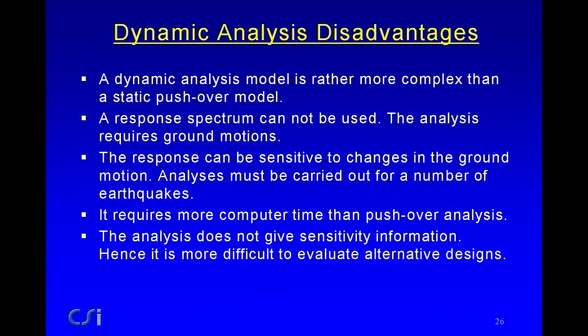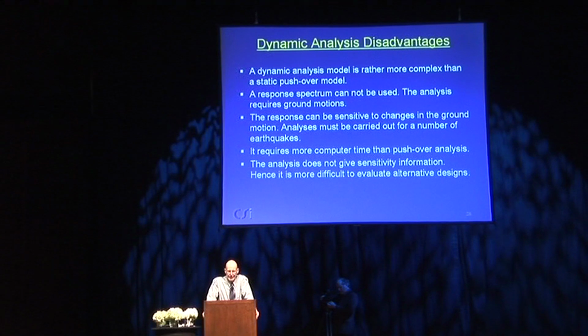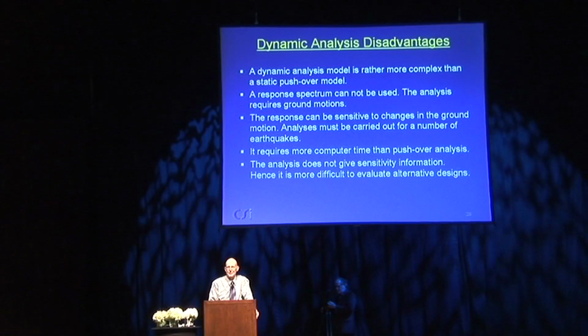Disadvantages: the dynamic analysis model is rather more complex than the static pushover model. Not a lot, but some. You can't use a response spectrum. You require ground motions. The response can be sensitive to changes in the ground motion, sometimes rather remarkably sensitive, unfortunately. So you have to carry out analyses generally for a number of earthquakes, and 7 is a common number, so it can get to be a lot of analyses. Each analysis requires more computer time than pushover analysis, and it doesn't give sensitivity information, so it's rather more difficult to evaluate alternative designs or decide what to do if something doesn't work.